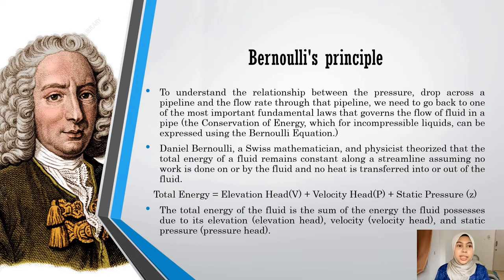Next, to understand the relationship between the pressure drop across a pipeline and the flow rate through that pipeline, we need to go back to one of the most important fundamental laws that govern the flow of fluid in pipe, which is the conservation of energy, which for incompressible liquid can be expressed using the Bernoulli equation.